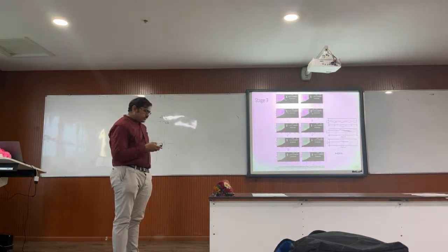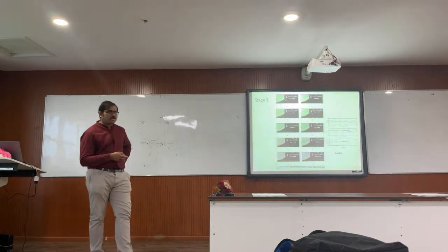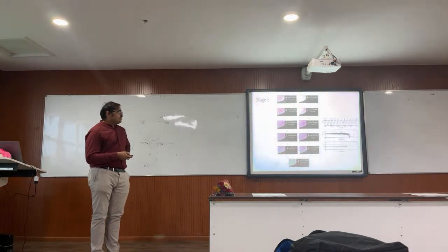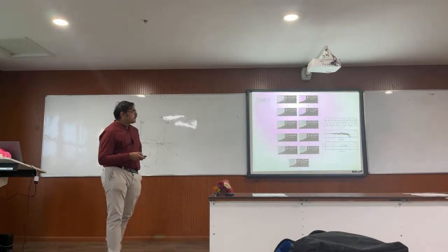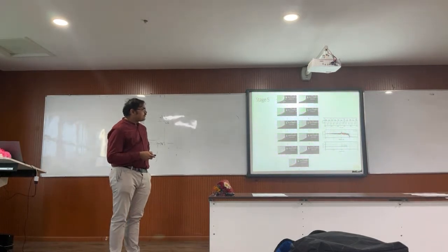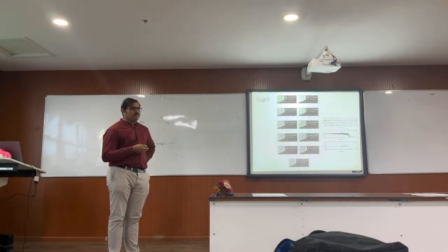Okay, and from here we could estimate the frequencies both from streaming as well as pressure measurements, and this frequency comes out to be about 474 hertz for this case. Finally, it goes into this full-blown unstart. You can see the amplitudes of oscillation are very high, very large change in pressure, and this has a peak frequency close to about 1000 hertz. So this high frequency as well as large amplitude.